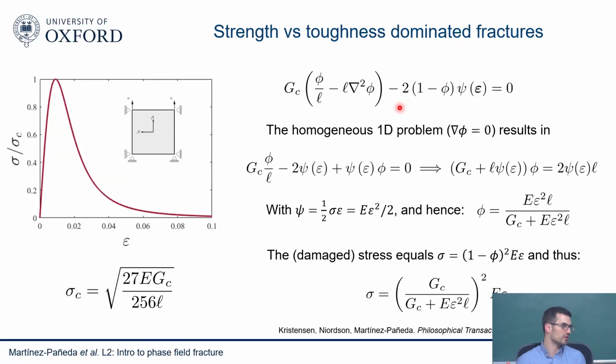This is what engineers normally do before phase fields, or they still do, when they are looking only at crack initiation. They will calculate G or K, the stress intensity factor, with a stress analysis, and they will then compare, and that will tell them whether a crack will initiate or not. Here I can model crack initiation and propagation just by having that G idea embedded into the phase field equation. So I don't need to calculate anything. I'm just solving this equation. I'll show you later how to do it. Some questions here and there.